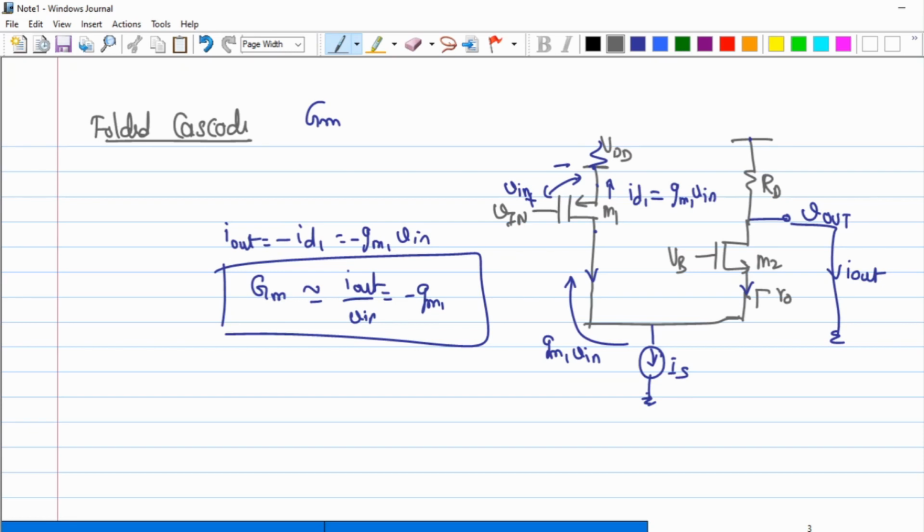Why does the source potential have to go down when I vary the gate potential? Think about the source follower. What is the literal meaning of source follower? Whatever the gate input is, the source has to follow it. So when I reduce the value of the gate input, the source node has to move in the same direction, in order to maintain the current. So now I'm comfortable that I can reduce the value of VB to small values. But VB cannot go higher.